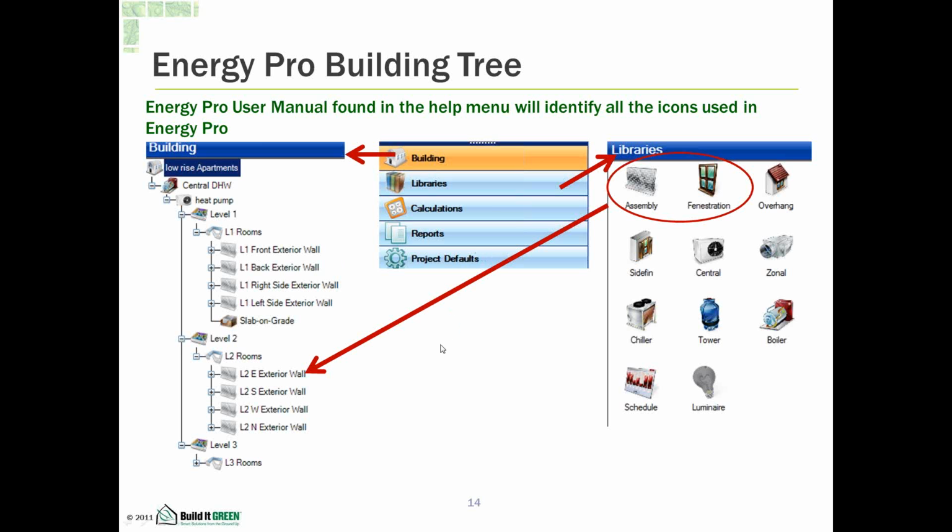So why include the common area? Two reasons: because I like to see the whole building in the energy model, and this common area has a play on what the residential building or portions of the building are experiencing. Then I feel like you should model it. But if it's totally separate and has no relationship with the building, then it doesn't need to be modeled. But that's just my approach to it.